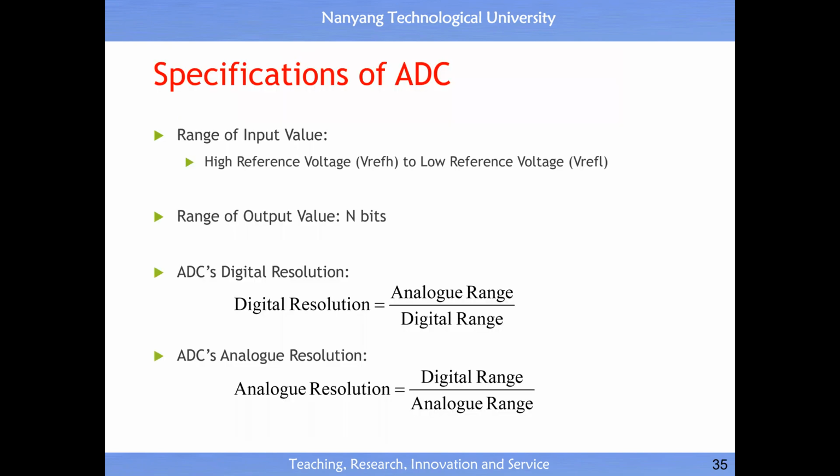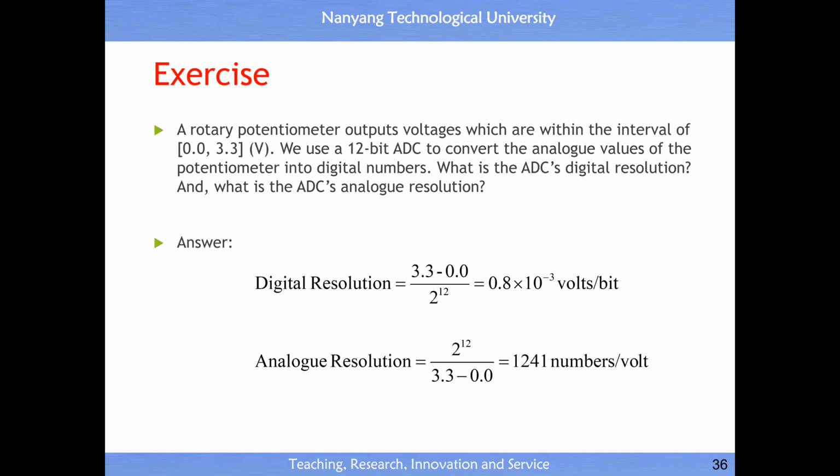All right. Then similarly, have some specification, sensitivity between input and output. This is quite easier for you to read. Okay. This is more exercise for you to play. This also gives you an indication for the ARM Cortex microcontroller. Actually, by default it is a sensor which measures voltage, and the range of the input is fixed. It's not like other microcontrollers that allow you to program the range. This one is fixed, always 0 to 3.3.